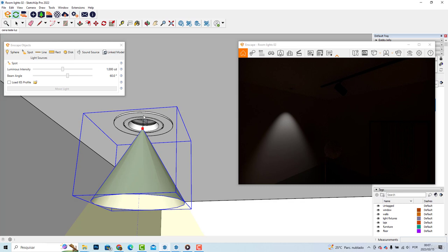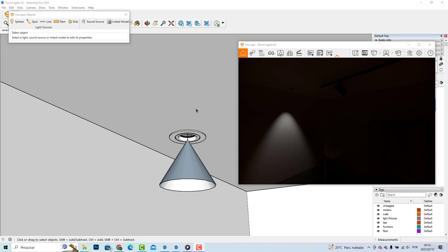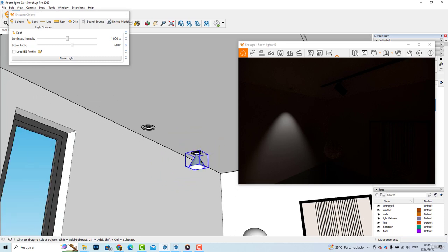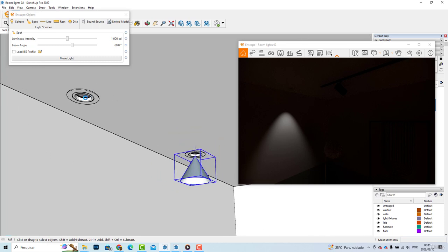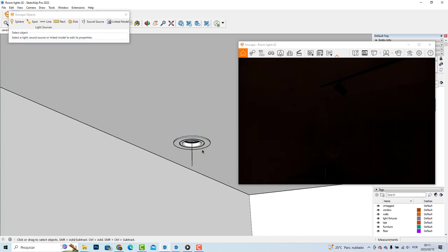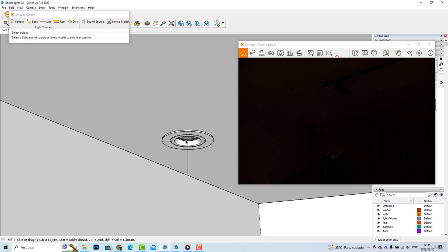location that we desire. And another interesting tip here would be to create the light inside of this fixture as it's a component. So if you take a look at our scene, we have the same object here, and they are components here in SketchUp. So any change that we make in one of them will be also done in the other. So I will delete this light here. I'll click and delete. And instead of creating outside, I will double click this component.